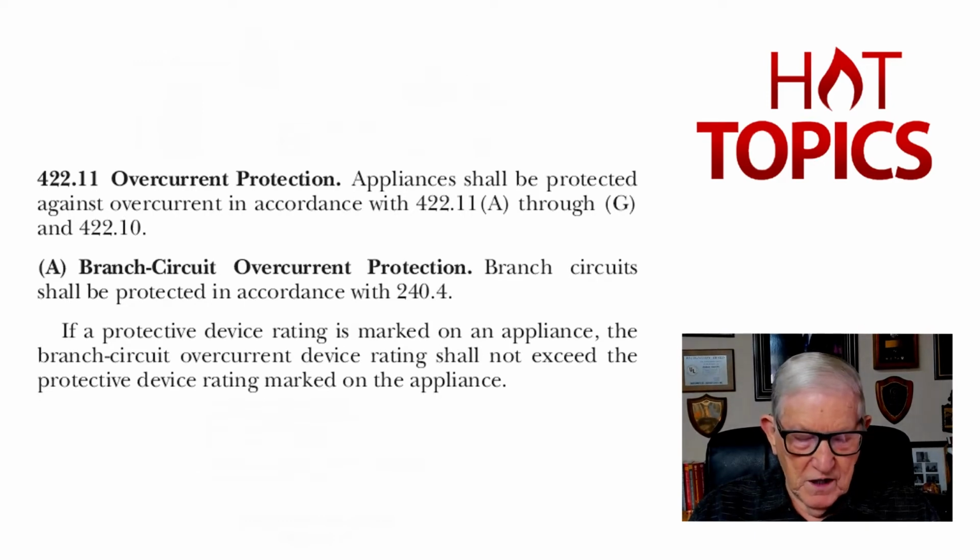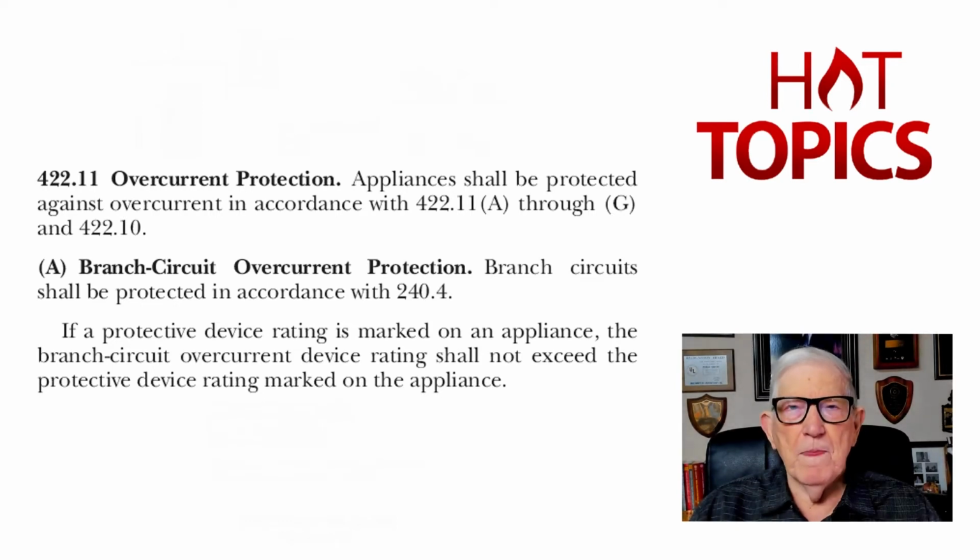But you always have to make sure that the overcurrent device is sized in such a manner you don't get a nuisance trip when all the heat is called for. Now you know that usually the heating element is subdivided. They can be in 5 kVA, and you would have kVA ratings of 5 kVA added together till you got a certain rating. For example, you could have 5 kVA ratings, and 4 of them, that'd be 20 kVA, wouldn't it?